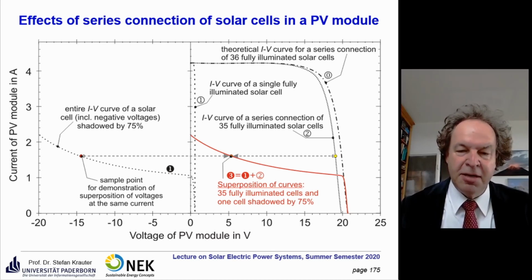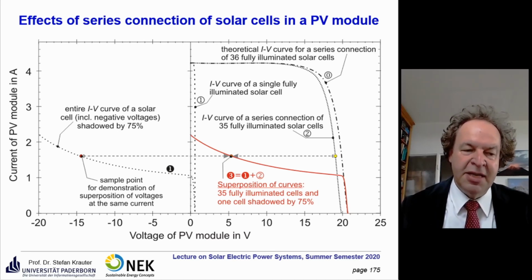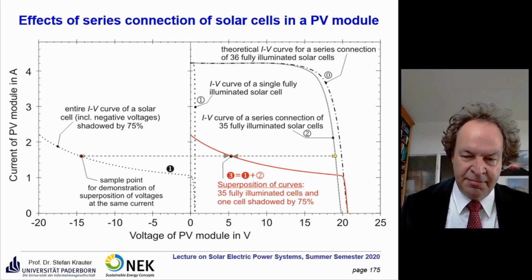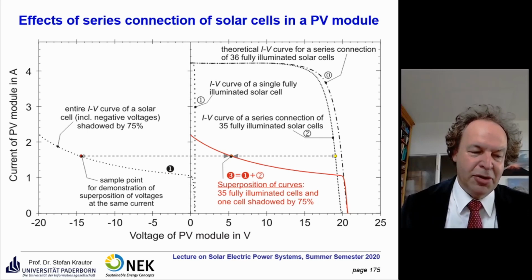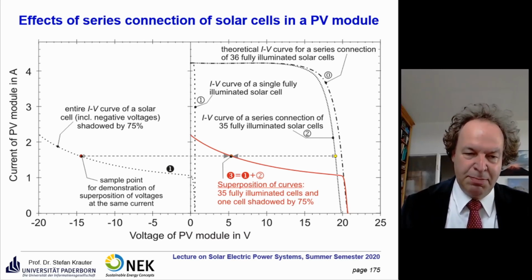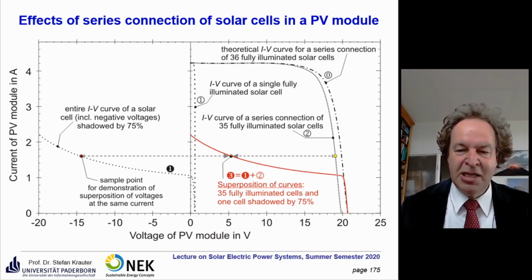It starts at a single point, called a hotspot, and then all the current goes through that one. While this point is very small, the current flow starts to increase and destroys that cell. The performance is then better because this cell is bypassed due to the hotspot, but you don't want your modules being permanently destroyed.